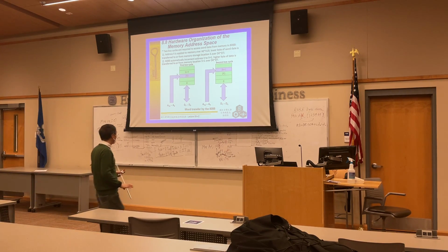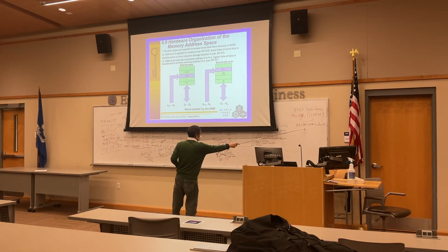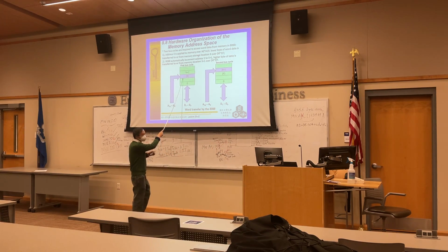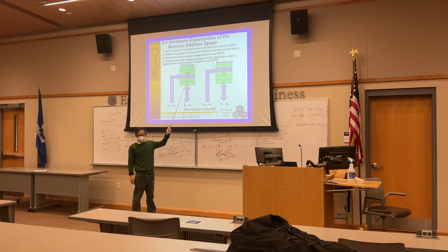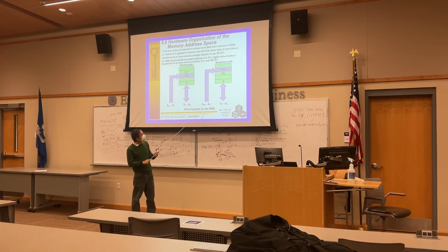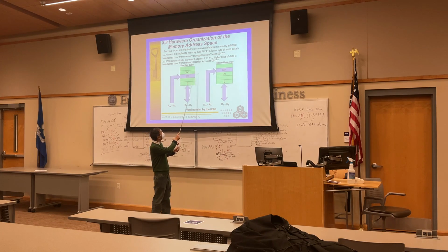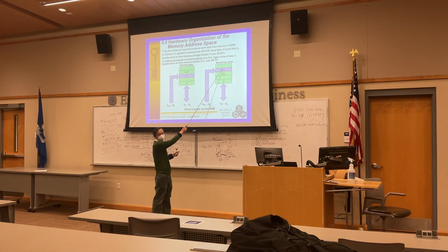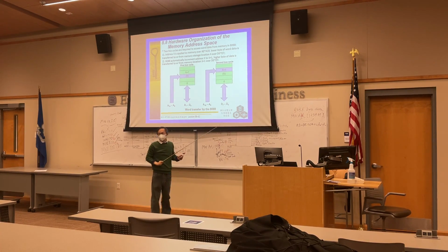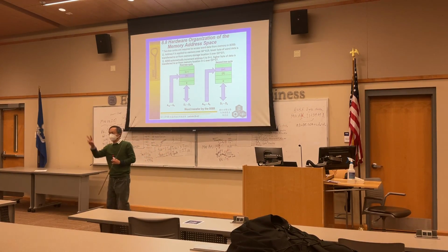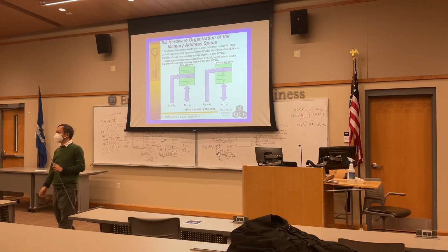Alright, so what's the procedure? You first calculate the physical address, broadcast it along the address bus, locate the lower byte of the data, and send it to the data bus, going to the microprocessor AL register. After that, increment your address by 1. What is the next byte? Locate the data, broadcast along the address bus, take it out to the data bus, and send it to the microprocessor AH register. 2 bus cycles are needed.